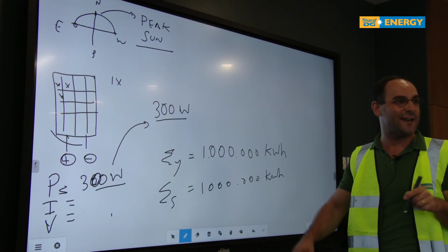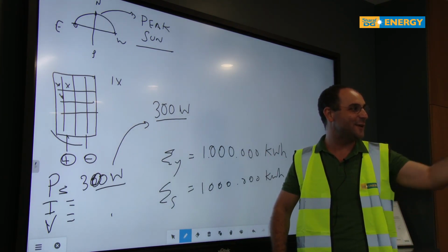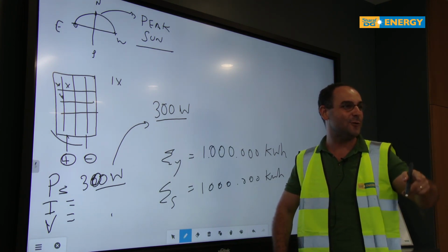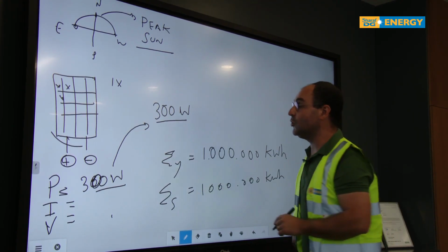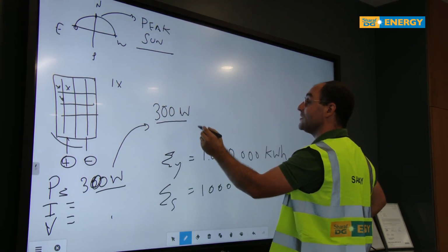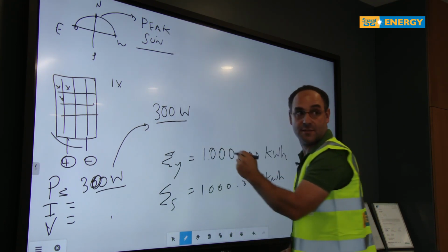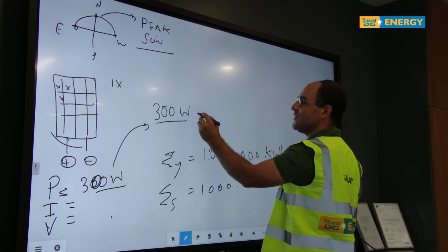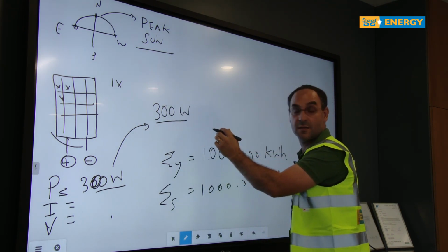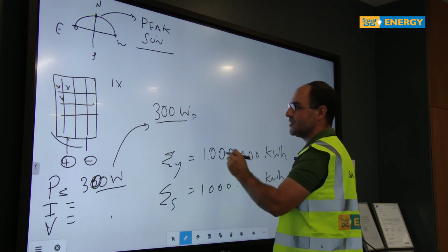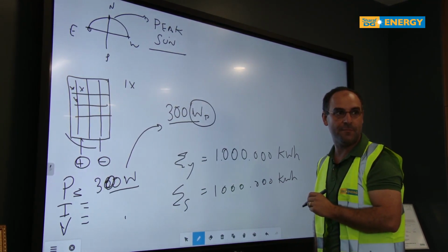It's not the supplier that says I produce 300, or in that case I would say I produce 500, you produce 100, Raul 400, and you guys will get lost, all right? So this is 300 watts in certain conditions, and that's in peak conditions, okay? Usually in the solar industry, we say this panel generates 300 watts in peak conditions. So we call this concept watt peak, okay?